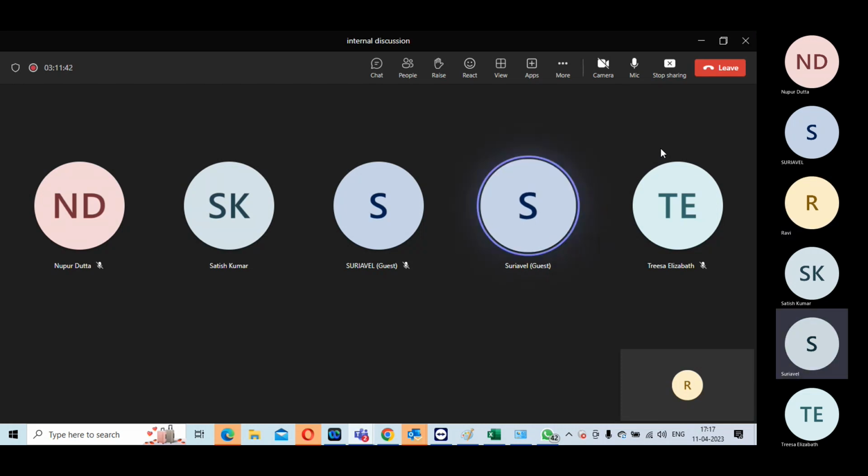So should it be false path or async? What is the difference between setting it as asynchronous clocks versus a false path, with set false path from clock group 1 to clock group 2, or set clock groups asynchronous?